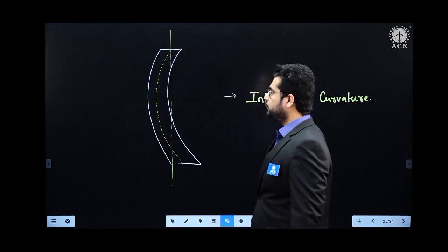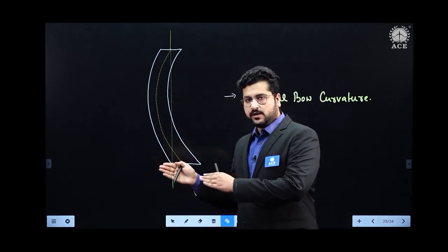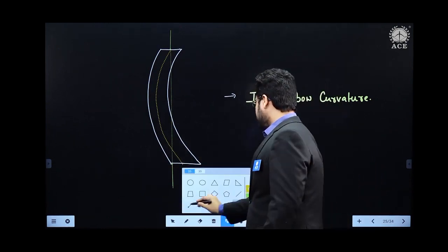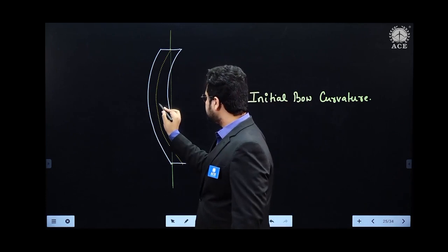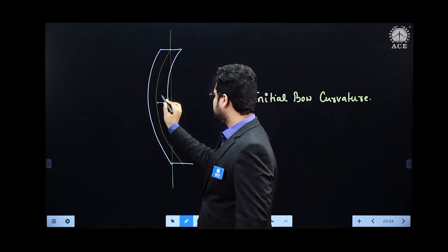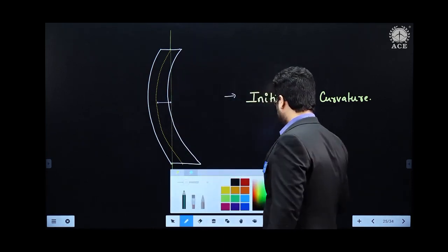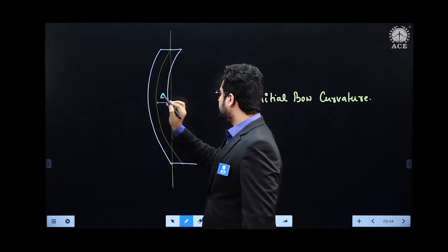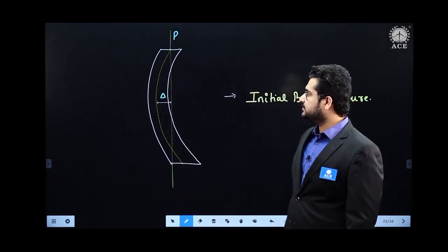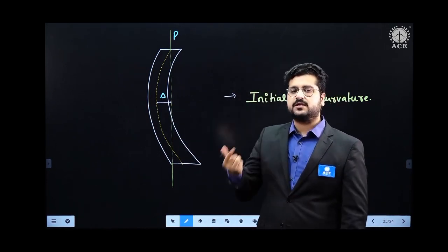All right, so due to this, what you can observe is that there will be a particular cross section where the centroidal axis would be maximum deviated from the line of action of loading, due to which you are getting a large eccentricity. There is some eccentricity because of this curvature, like this. There is some eccentricity, delta you can say, which is already present, and let the load be P. Now because of this, the member, in addition to the compressive load, is also subjected to a moment.